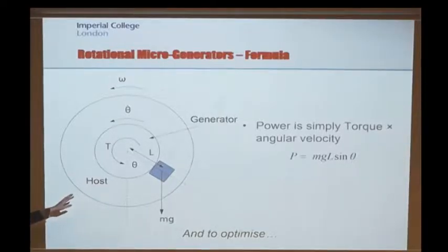And the way that I would control that is by having a variable resistance type device attached to the harvester itself, so that I can control the current that I'm pulling through the windings of the generator and therefore control the torque. So there's very much a system here where I'm using an electric circuit to control the mechanical properties of something. And I know what the mechanical properties are that optimize the power density of this particular structure, and so I need to control the electric circuit to give me the right mechanical properties to maximize the amount of power that I can generate.